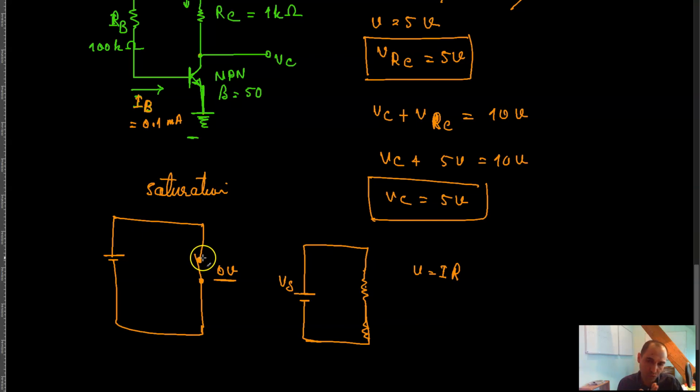In a mechanical switch, when the switch is open, the resistance across the switch is infinite. When the switch is closed, the resistance across the switch is 0. And therefore, when the switch is closed, then you have 0 volts voltage drop across it.